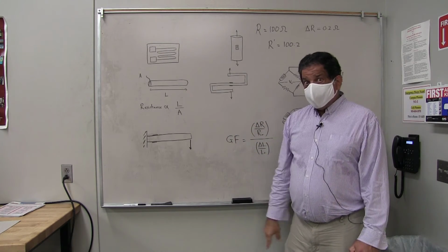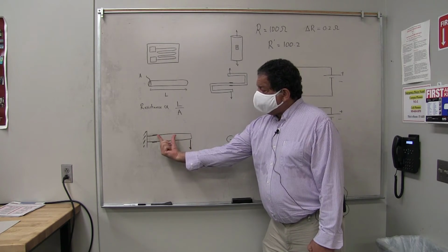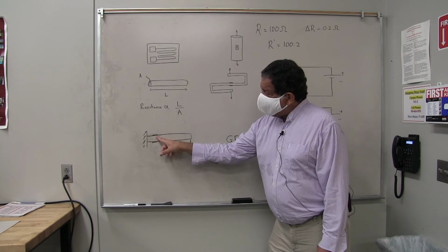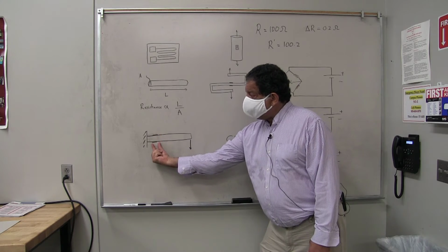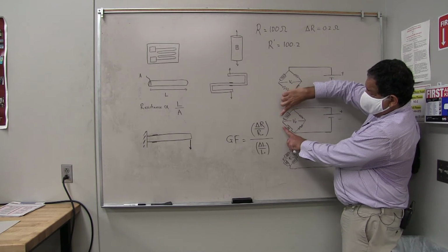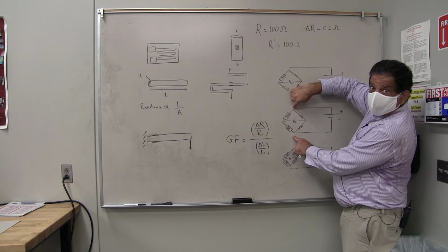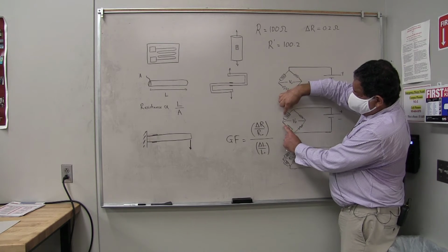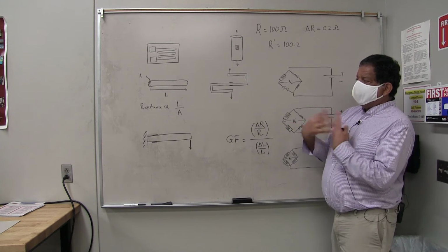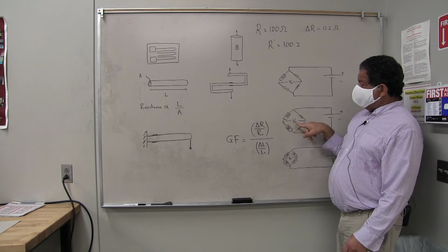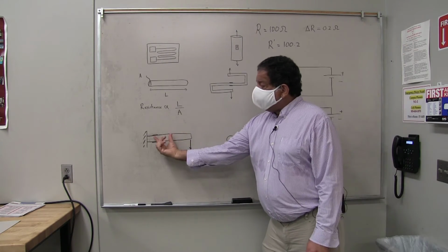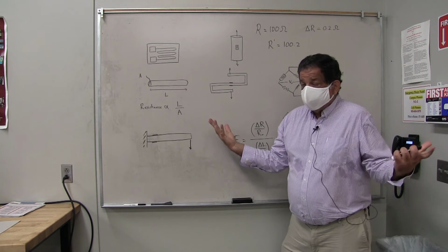What about those other 2 deformations that we talked about? Well, if I have thermal expansion, both of these are stretching. Right? So what that means is that this one increases in resistance, but this one also increases in resistance. And that means that this is still going to be exactly the halfway point between these 2. So the fact that I have a positive and a negative strain gauge over here, both getting stretched, cancels that out, and I still read 0.